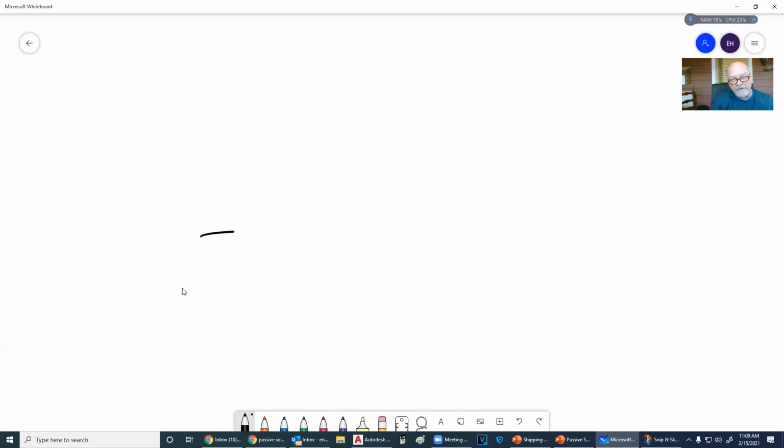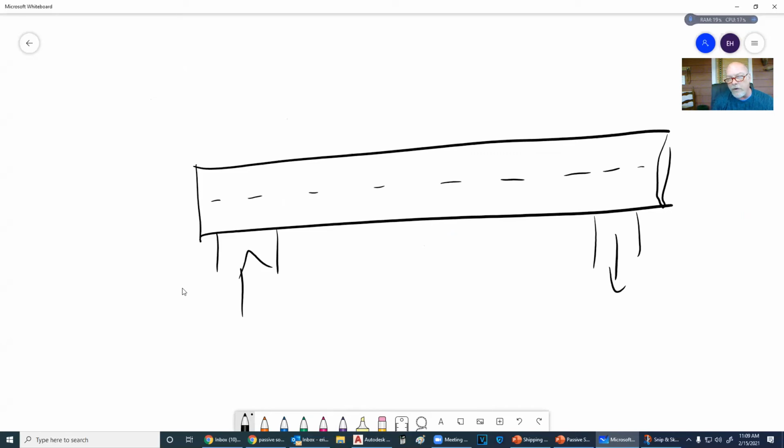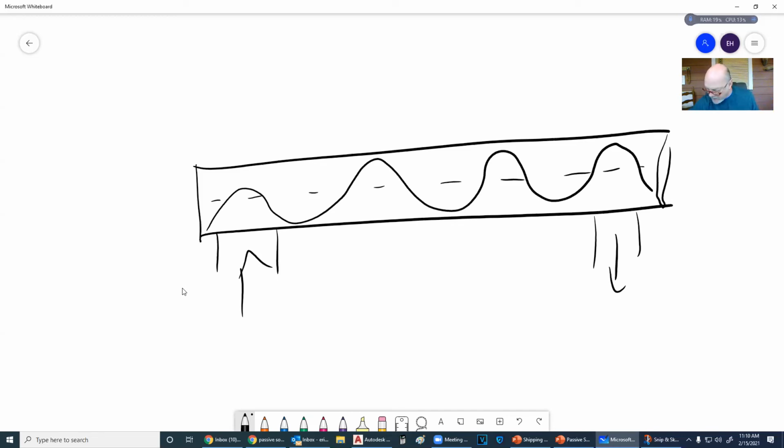So the student at AB Tech built one, and I've actually got this in the classroom. He put that metal mesh in there, but when he put it in, he had it exactly straight. So he's got an opening where he pulls air in, and an opening where air comes out, and this was to go up on a wall or something. Don't put it straight. Make that thing curve, so that way the air flows in and around that and pulls off the heat and gives it to the air.